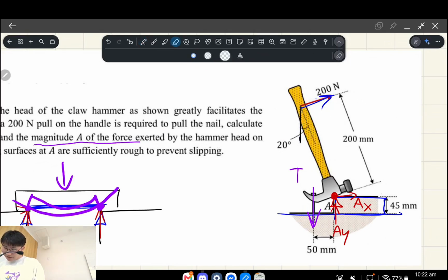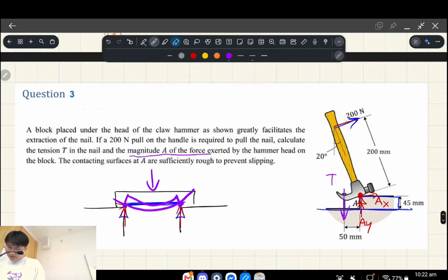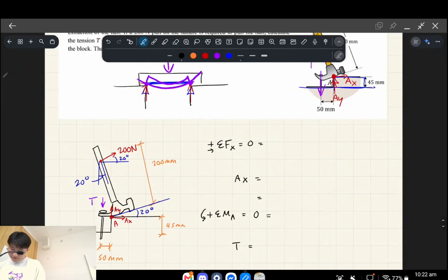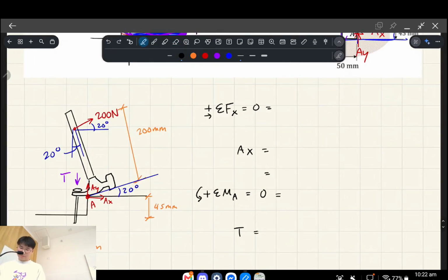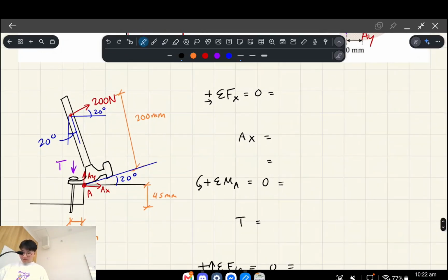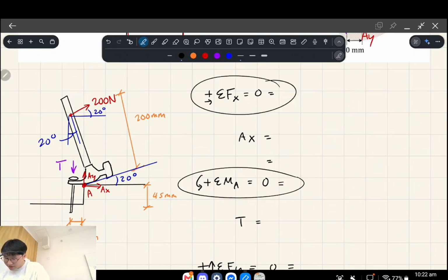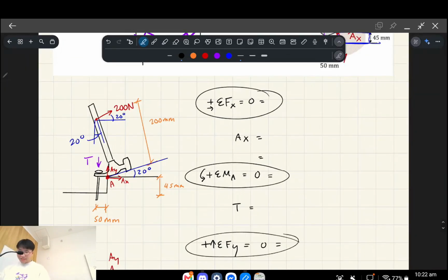Yeah, these are all kind of equivalent angles, right? And so what I've done in my free body diagram is I've just drawn 20 degrees everywhere. That might be useful. Okay. So now the next question is essentially what path do we go down in terms of our equations of equilibrium in order to solve for these support reactions, right? So you've got the sum of the forces in the x direction or y direction or the moments.